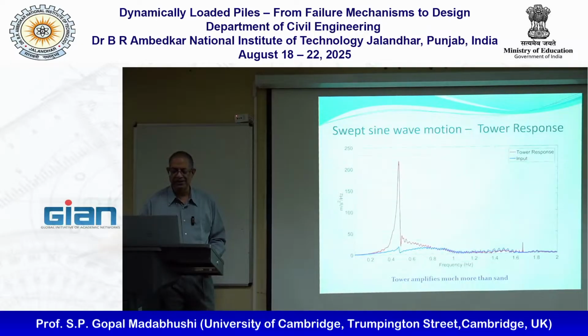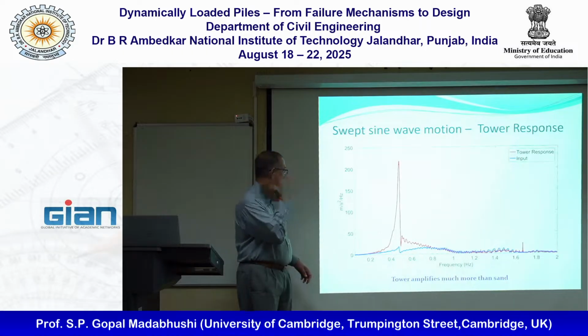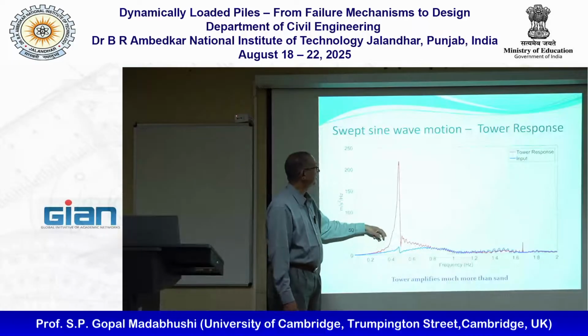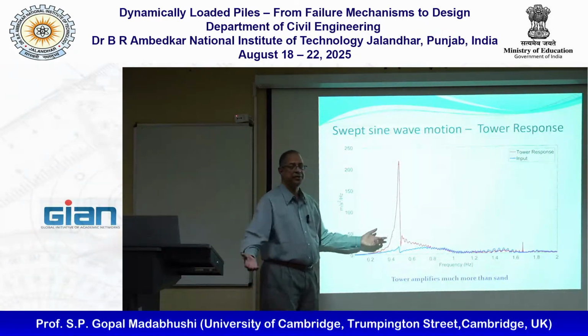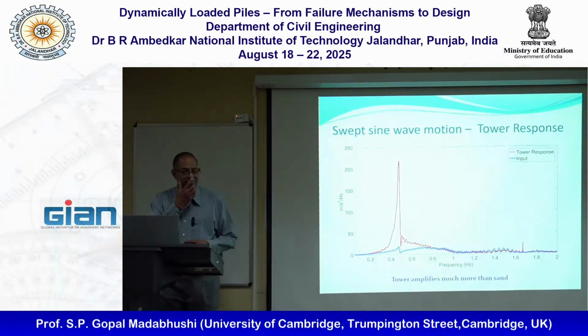You also can then do the fast Fourier transform or response vector, and you can see what the input motion I applied was and what my tower did, and you can see it's massive at that frequency. Therefore, you know that is your resonant frequency. Okay, so this is an example, but we do this routinely for everything.